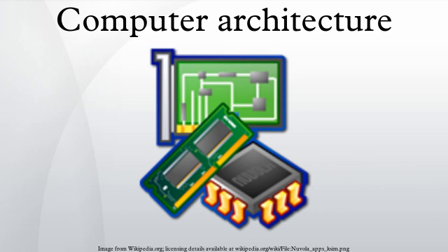Implementation can be further broken down into several steps. Logic implementation designs the blocks defined in the microarchitecture at the register transfer level and logic gate level. Circuit implementation does transistor-level designs of basic elements as well as of some larger blocks that may be implemented at this level, or even at the physical level, for performance reasons. Physical implementation draws physical circuits. The different circuit components are placed in a chip floor plan or on a board, and the wires connecting them are routed.